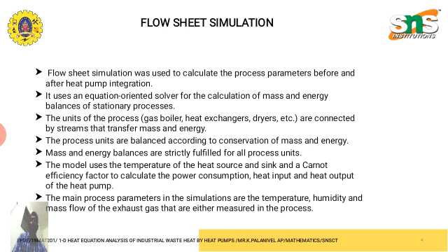It is not necessary to specify the refrigerant or type of compressor in this model. So it can be used for potential assessment in a wide range of temperatures. The Carnot efficiency factor was chosen as 0.50 because experiments with a laboratory prototype of a high temperature heat pump have shown that this factor can be expected with an optimized heat pump.